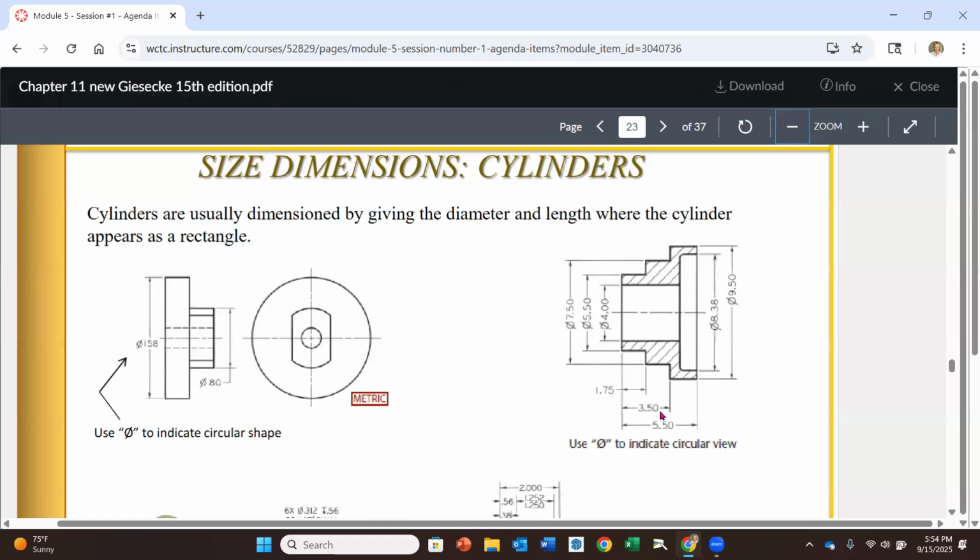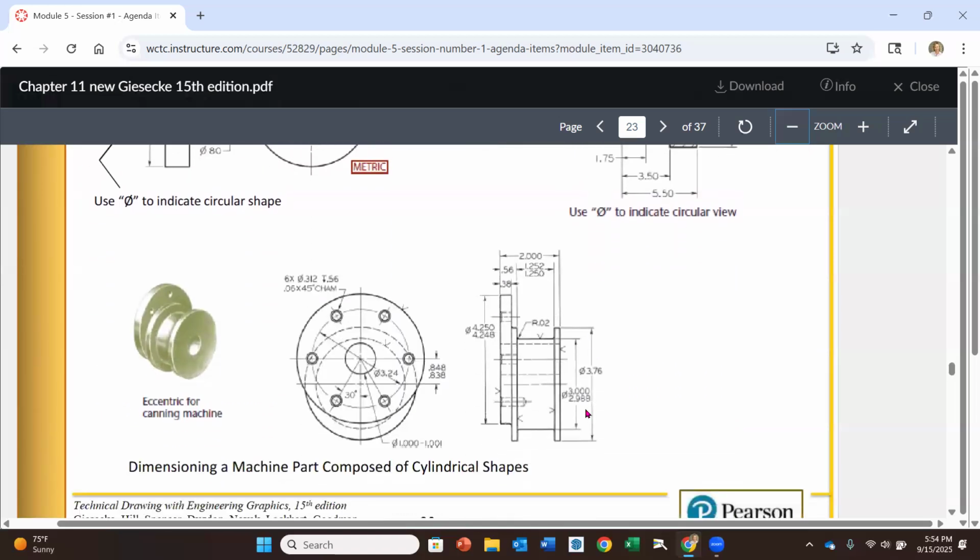Dimensions are vertical. Right. So Carlos said the dimensions are vertical here. We got to turn our head, if you would, to see them. They all need to be horizontal, and then we would stagger their values. Okay. One to the next. This is acceptable in ISO standard. ISO is International Standards Organization, and they kind of oversee, if you would, everywhere else except Canada and America. Okay. So you may see those if you are getting prints from companies from around the world. Okay. So they just operate underneath a little bit different standard than we do.